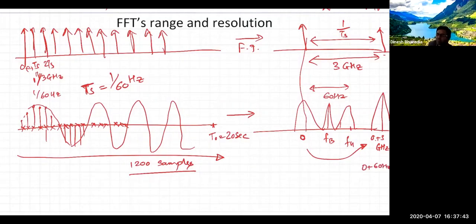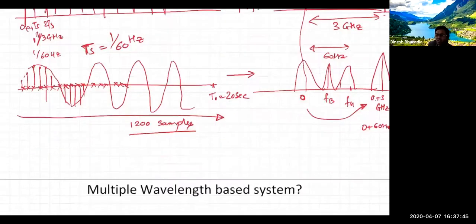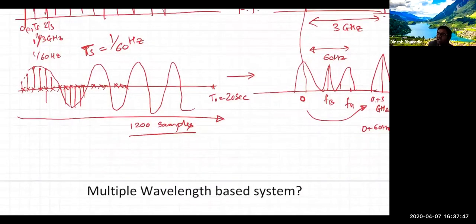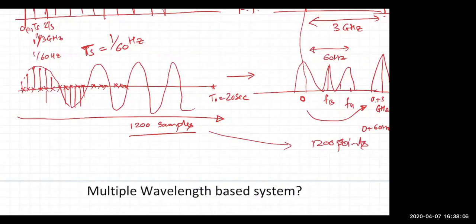What happens when you do FFTs? First of all, not just are the time domain samples discrete, even the output you have from the FFT is also discrete. How many points do you get when you take a 1200-point FFT? You get 1200 points. Correct, everyone? Yes.